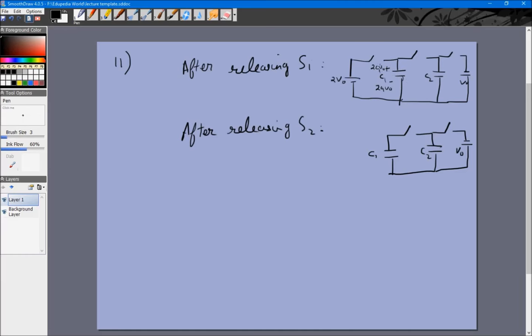But okay, both of them actually have a capacitance C. They just, the names are different, so we'll just write this as 2CV0. So I won't solve this. You can see directly that this will be plus minus CV0, and this will also be plus minus CV0, because then they both have the same potential difference across them. You can just solve it and try to do this. So take this Q1, this Q2, Q1 plus Q2 will be 2CV0, and Q1 by C will be Q2 by C, which means they'll be equal.